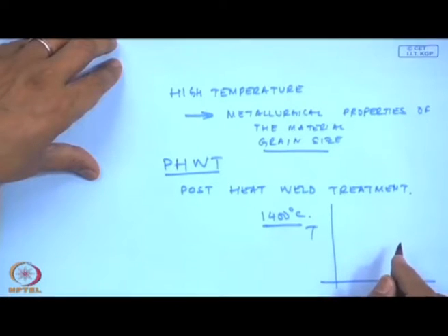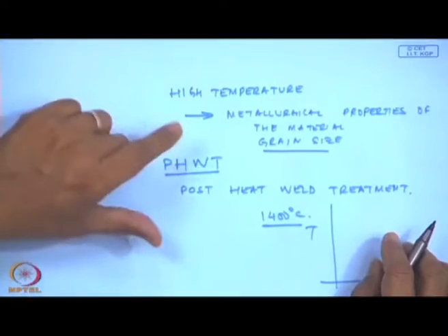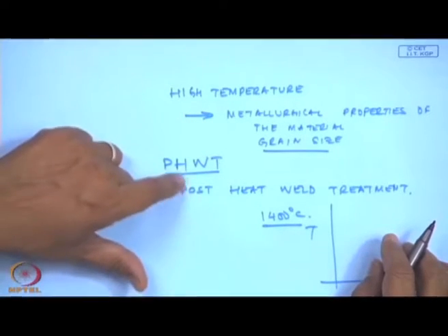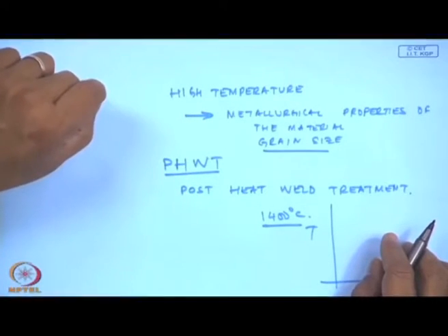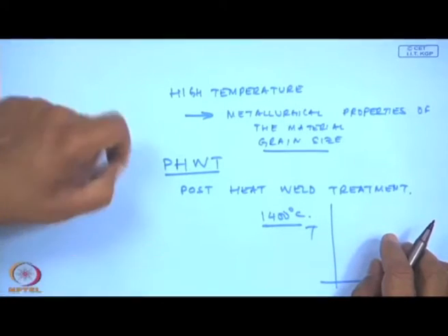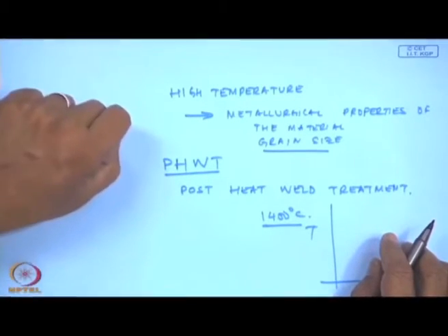So, sometimes the materials can become brittle, sometimes they can crack, sometimes they become so brittle that they cannot sustain large fatigue loadings and they would fail. So, after a post heat weld treatment, to ensure that there are no voids, no cracks, no defects, it is mandatory in such critical applications in pressure vessels, nuclear plants, bridges, etc. They do 100% ultrasonic testing.